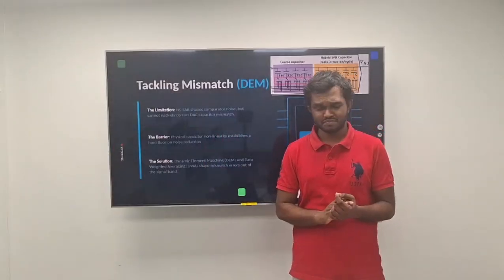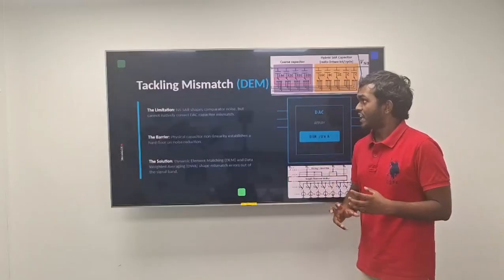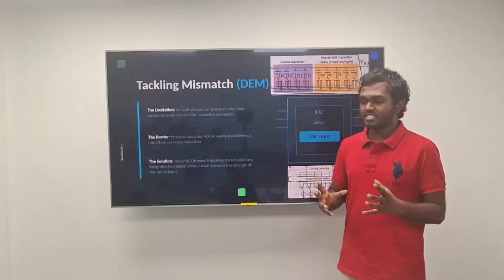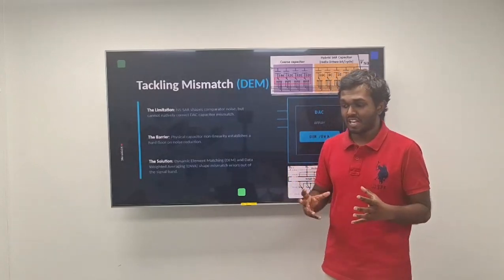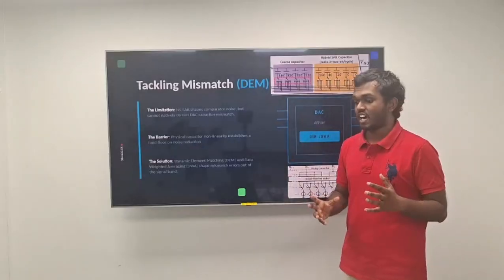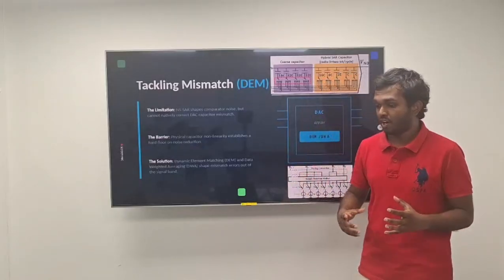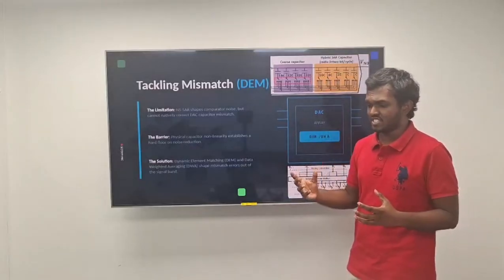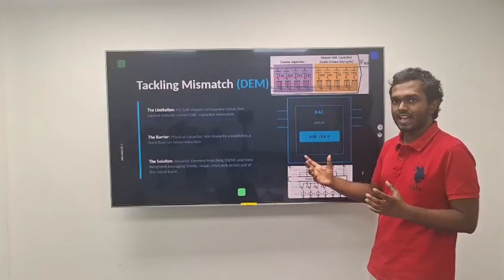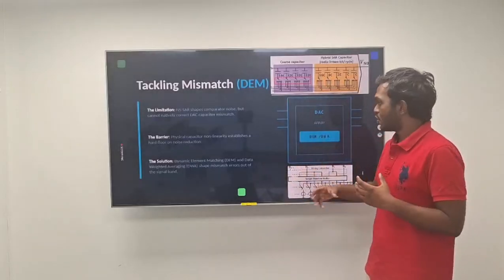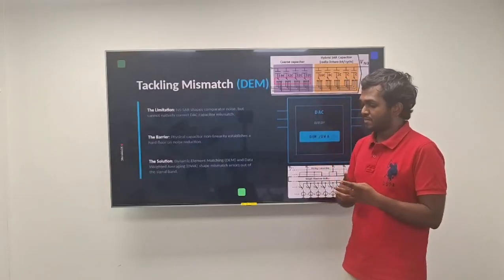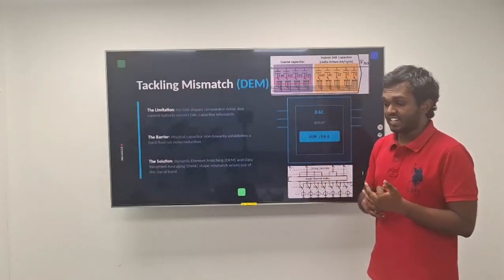Okay, thank you, Kavishkar. In my next slide, what I'm going to talk about is how to tackle the mismatch in capacitors. Noise shaping is good at reducing noise, but it has a big blind spot. The tiny capacitors inside the DAC are never perfectly identical coming out of the factory. Those small mismatches give errors in noise shaping. So the IC designers have to use some methods to improve that. They have used two methods. First one is dynamic element matching and second one is data weighted averaging.